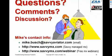It puts less stress on everything to have it turned on before you start, although again, this is not a huge deal. The two times that I would consider starting the airplane with the alternator turned off, one is if you're starting on auxiliary power, on ground power, as opposed to on the ship's battery. Normally when you're doing that, the procedure is to turn off the alternator, turn on the battery, plug in the power cart, start the engine, have the power cart removed, and then turn the alternator on.